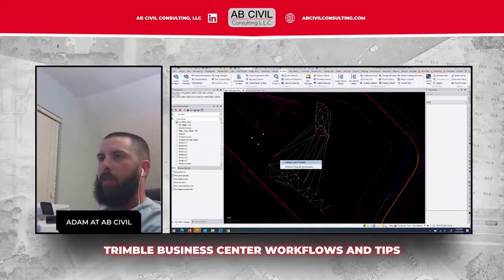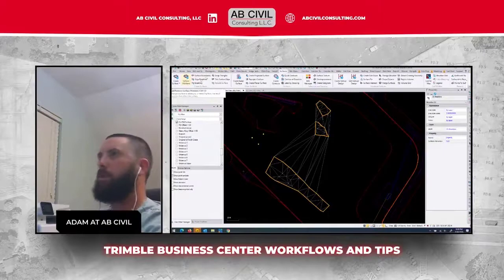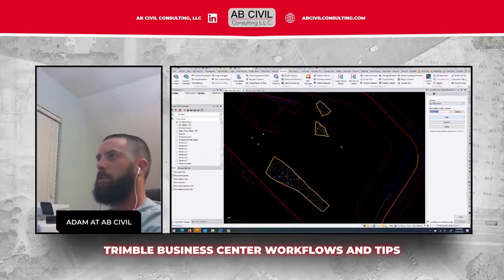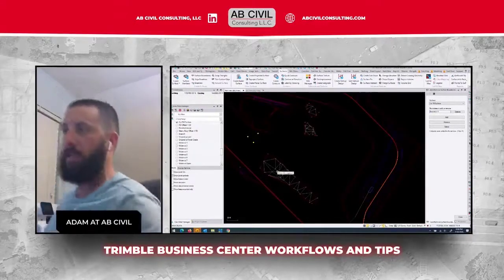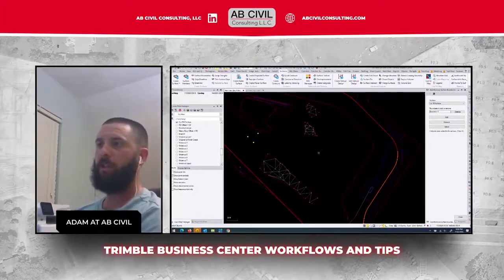So I'm going to click on these edge break lines. Then I'm going to go up to surfaces, and instead of surface members, I'm going to do surface boundaries. And the surface I want to add them to is the cut fill surface. So when I add it, it just added all 3 of those boundaries, and it made each of what were separate surfaces the same surface, but I added 3 boundaries so that they're still on their own.